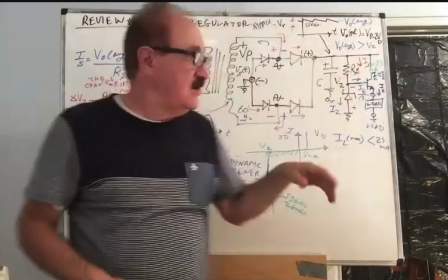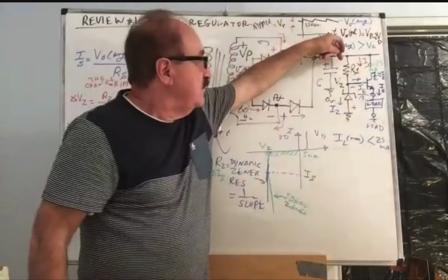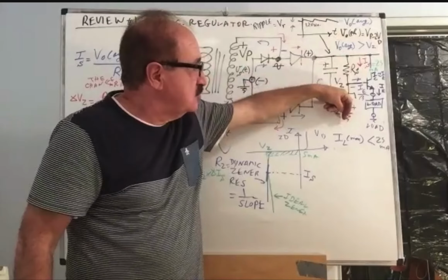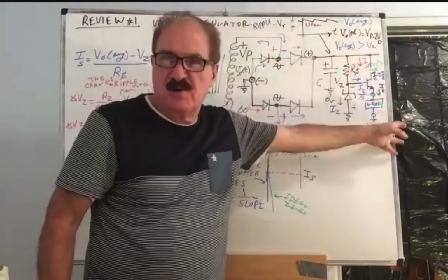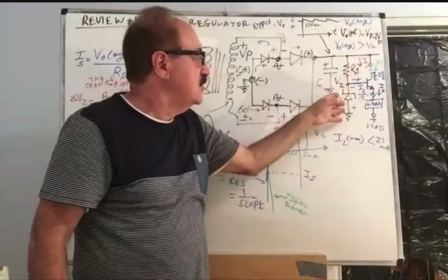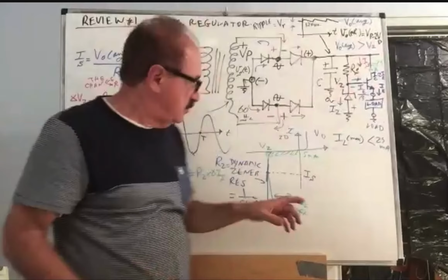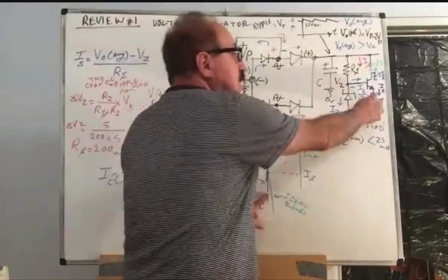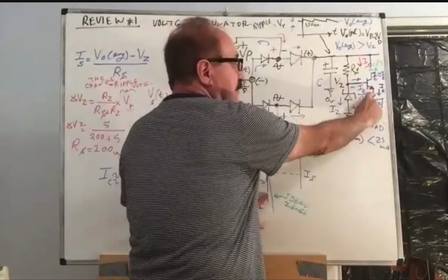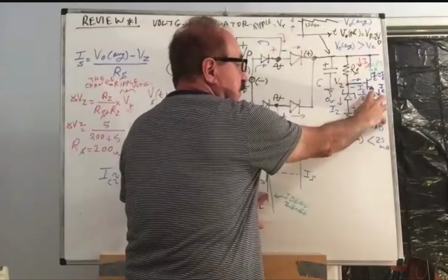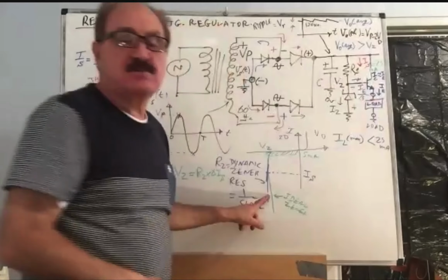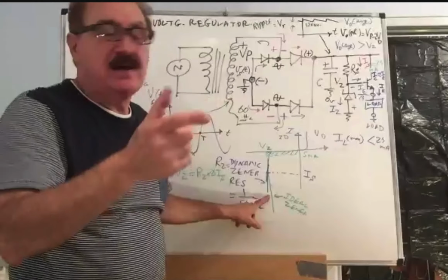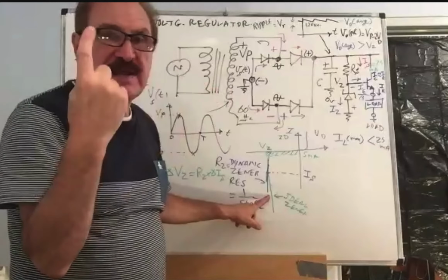That's great, because if you were sending 25 milliamps, all of the 25 milliamps goes through the Zener with no load, zero base current. Now, if you're drawing 100 milliamps in this path, your base current is going to change by 100 milli divided by beta, which is like 1 milli.